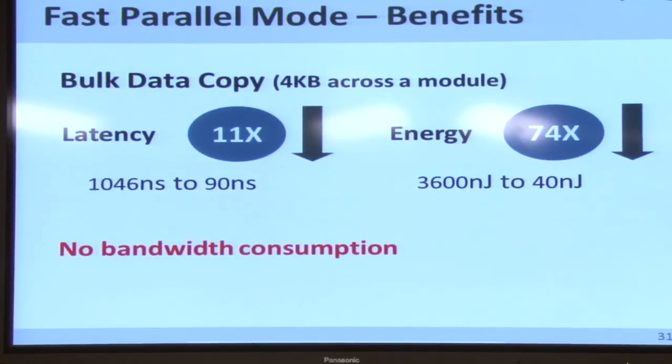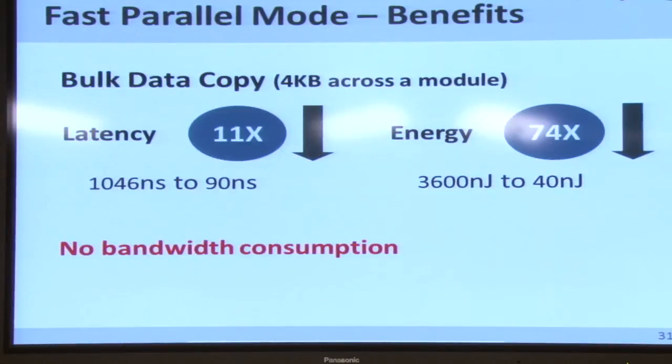Or you could write back first and then copy. That's a simple mechanism, right? I can say, okay, before I start the copy operation, I'm going to check if the source page has any dirty block at all. If it has any dirty block, I'll first flush them all to DRAM and then perform the copy. A very simple mechanism, right?